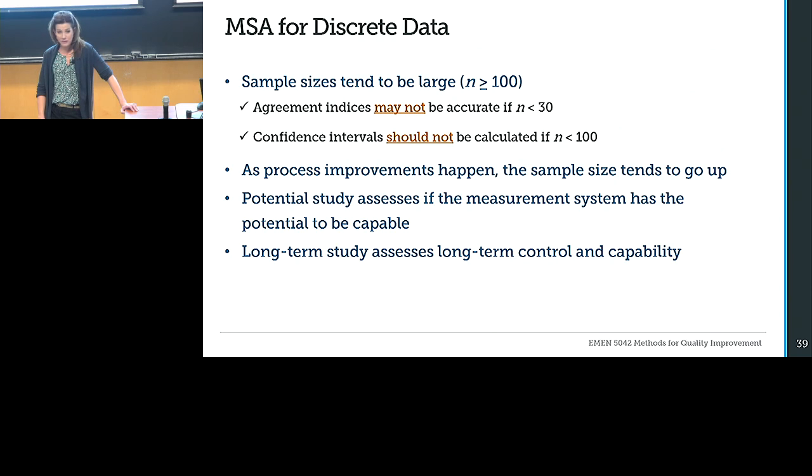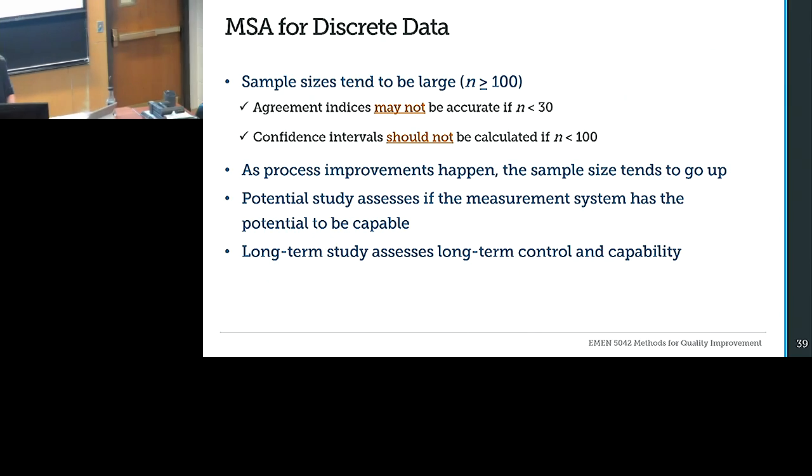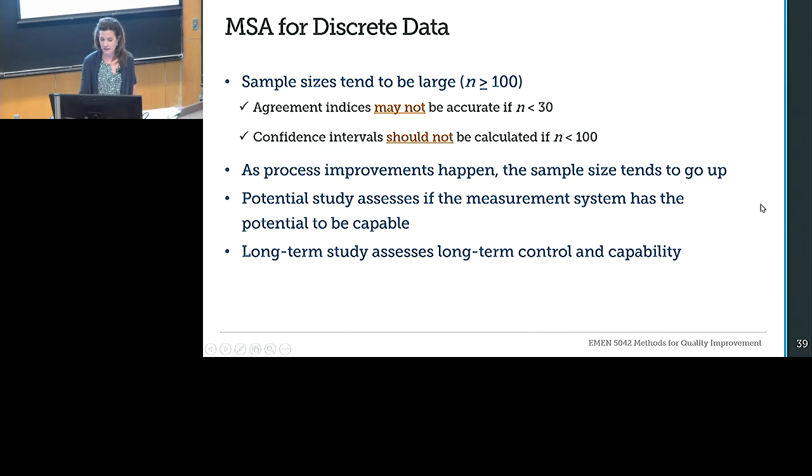When we do our measurement study, you'll want to do a 50% defect rate. I'll just go ahead and tell you right now because you won't pick up the differences otherwise. I'll tell you again next semester; I don't expect you to remember that. But when you're doing this kind of study, when I had those 1,000 lids, I think I had 3 in there that were bad, because that was typical of what they would see for proportion defective. The machine had to pick out the 3 bad ones, and after 2 weeks of tweaking, we finally got it to be able to do that.